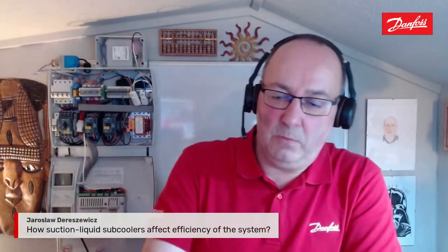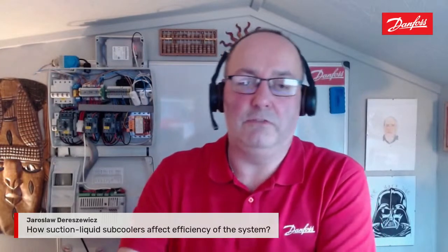In simple terms, and as I said, I try to look at things very methodically, so to speak. If we think of a suction liquid heat exchanger, we are ensuring that we are subcooling the liquid, which is good. So we have subcooled liquid hitting the expansion valve, which gives us the correct capacity. We don't get excessive flash gas. But on the other hand, we're also warming up the suction gas. So it gives you a benefit. I can't tell you from a percentage point of view how much.